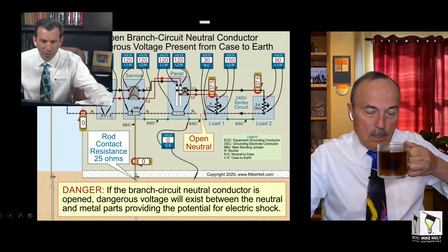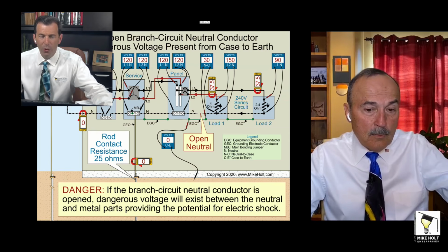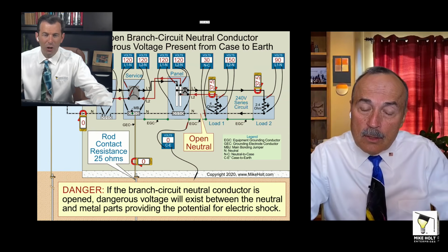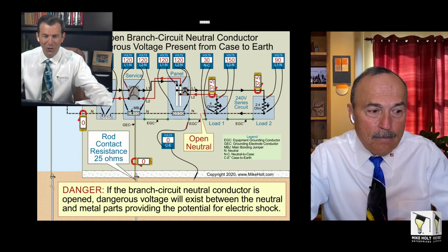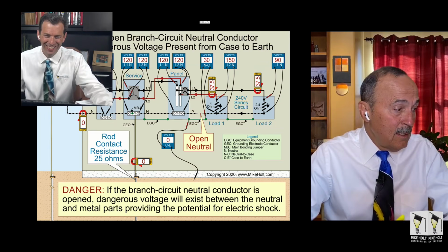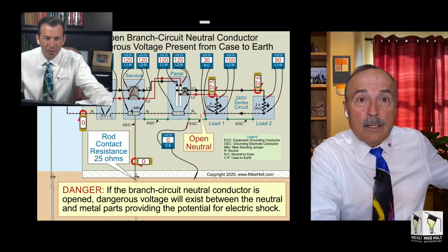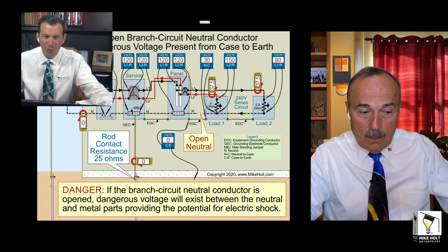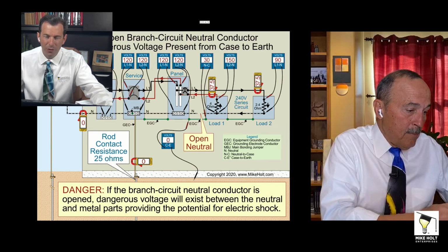Let me see what else. I think we might have one more. Research put a comment: "Hey, guys, give us some more. Manholes are not within the scope of Article 314." We know, research. But it was still a good question. Yeah, we know 314. And by the way, another comment from research. Somebody got something for us? 314.30(D) does require the cover to be bonded. Metal covers and other exposed conductive surfaces shall be bonded.